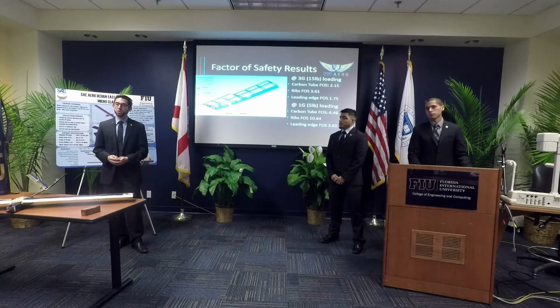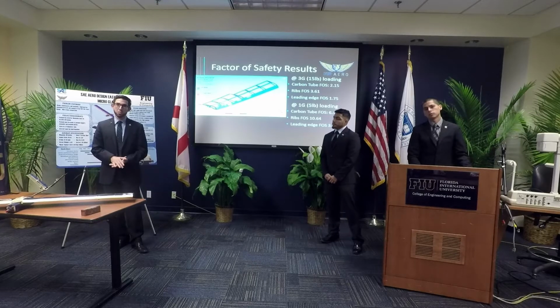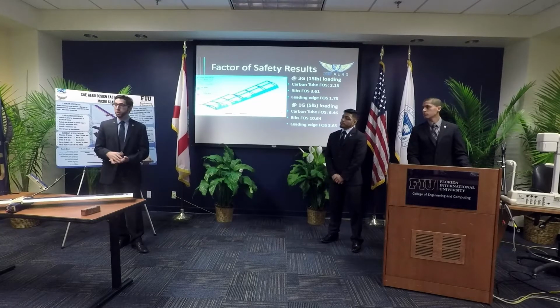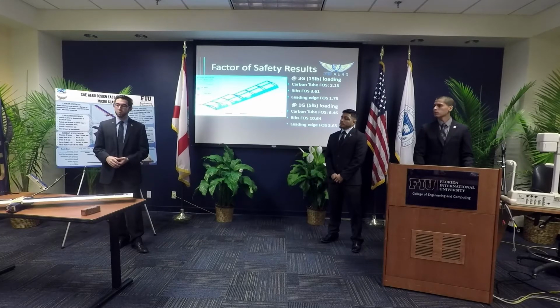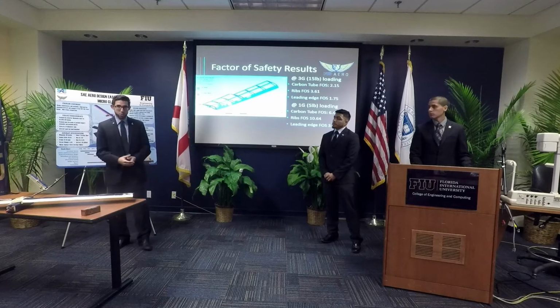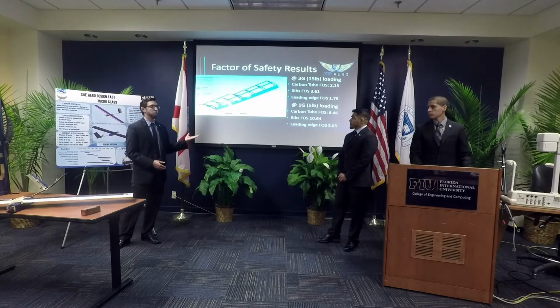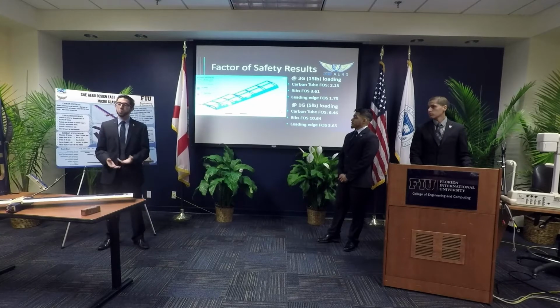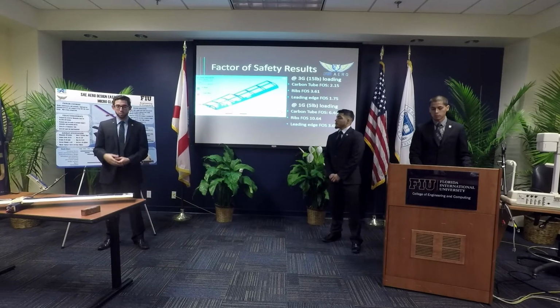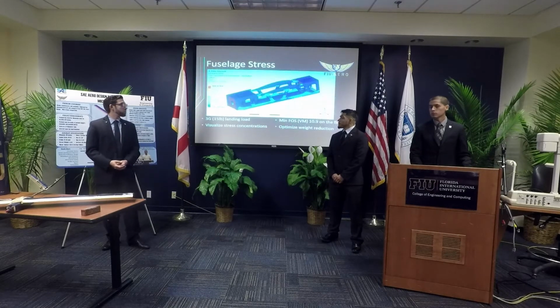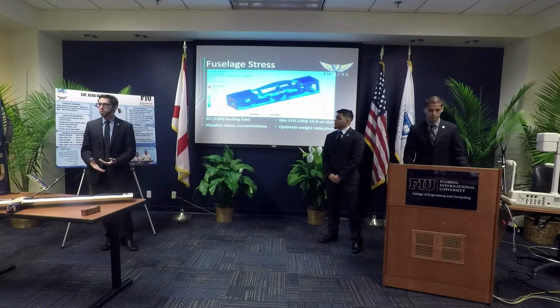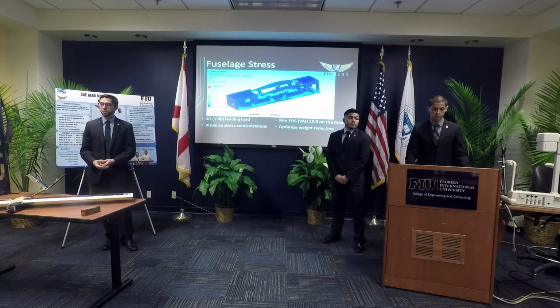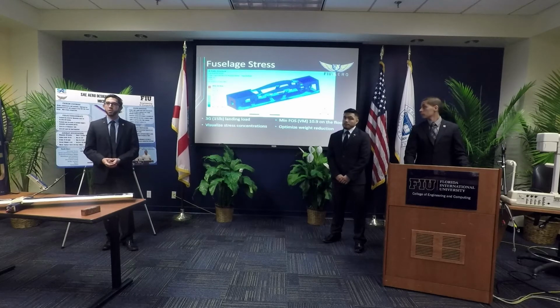For wood, we were fortunate to find a USDA source of material properties that allowed us to treat wood as a realistic orthotropic material, the way it is. And because of the complexities involving carbon fiber analysis, we had to assume linear orthotropic behavior as well. However, we got relatively high factor of safety numbers. The lowest is 1.75 on the leading edge, which, once you add the Ultracoat, will become way higher. Because we're belly landing, we had to do some analysis on the fuselage. This allowed us to minimize the structure that we didn't want. We used fillets wherever we could to minimize stress concentrations.